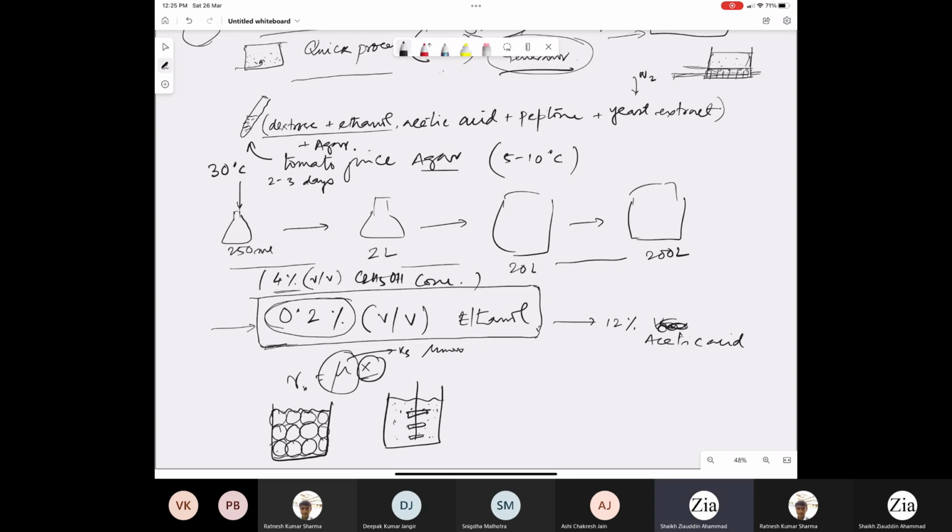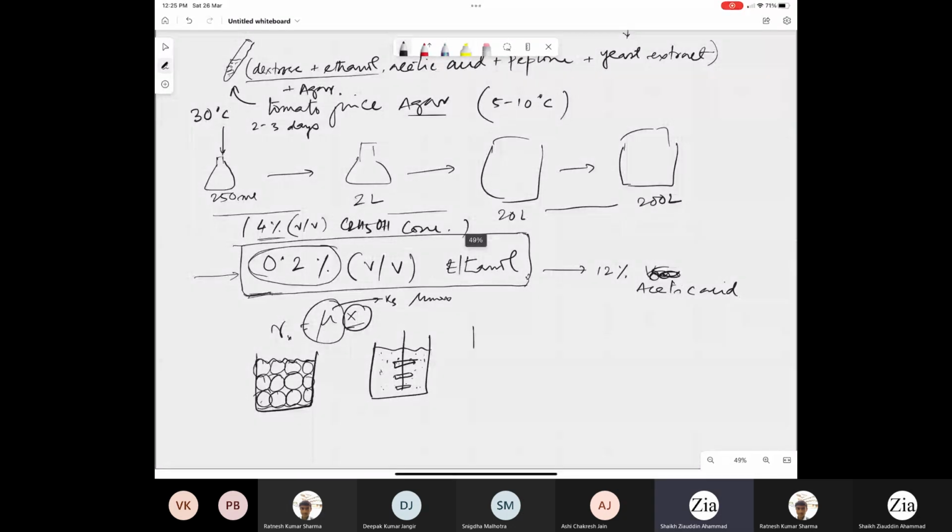So mechanically, you can agitate and have a little bit higher concentration of liquid. It is actually very different from the earlier design, because the earlier design is a simple tank without any stirrer. So there is always a tendency for the higher biomass to settle, so it will go out of the system and have very minimal interaction with the liquid. Whereas here, you are forcefully keeping it suspended in the liquid, so we'll have better transport of nutrients, and the transfer resistance will be minimal. Then you can get much faster production.